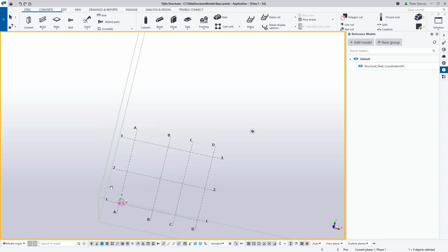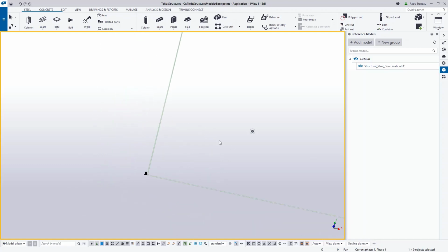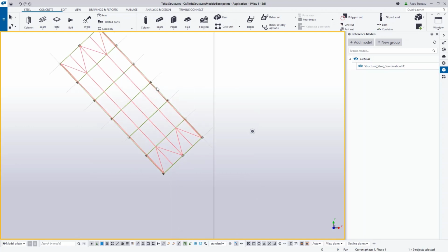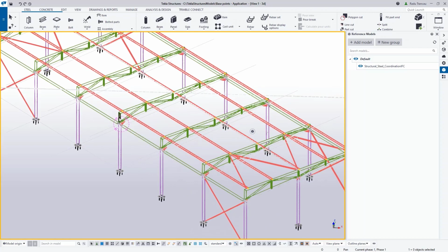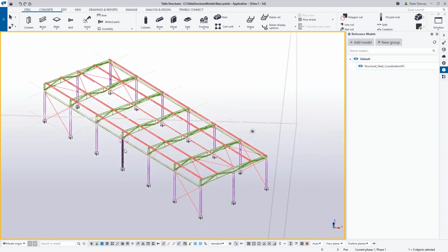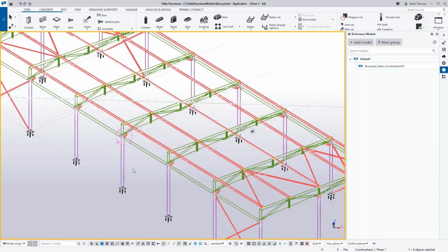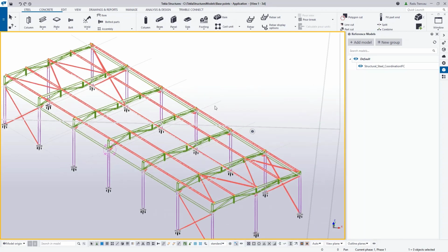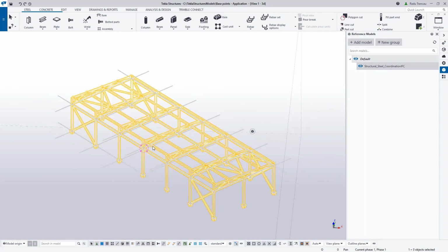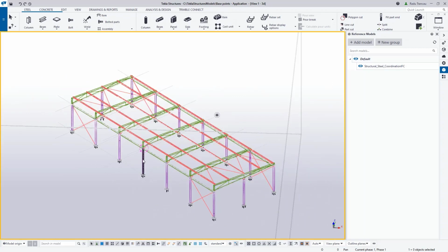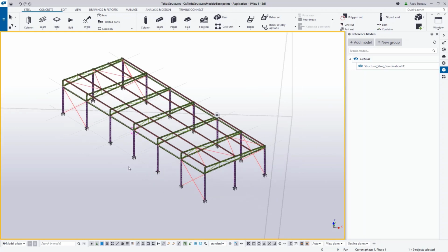Okay, so instead of just doing this model here and start the modeling, you will need to import that model next to Tekla's origin. That is a very common mistake that I've seen getting asked through support, and I will quickly demonstrate you what happens if you start modeling at this distance. So let's say the majority of people will just start modeling over this IFC straight away. Okay,